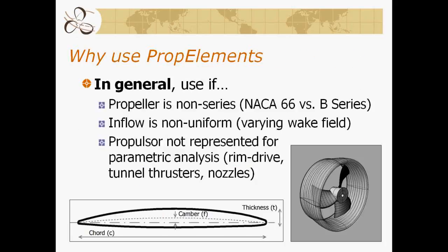Okay, so given that brief introduction to the tool, why use PropElements? Well, we would use it in general if our propeller is non-series, such as if we were designing a NACA 66 foil-based blade versus a B series or a GON. If inflow is non-uniform, if a single wake fraction number does not do a good job at representing the calculations,